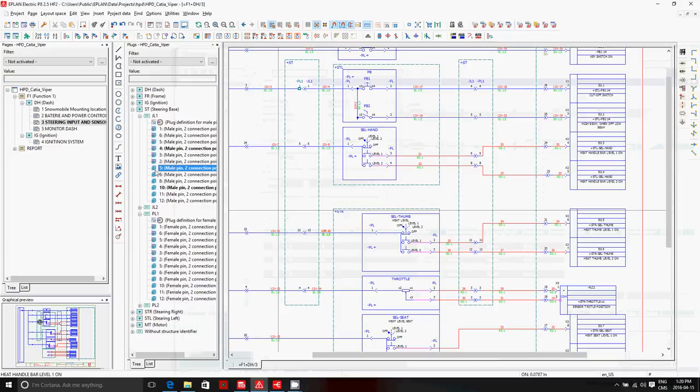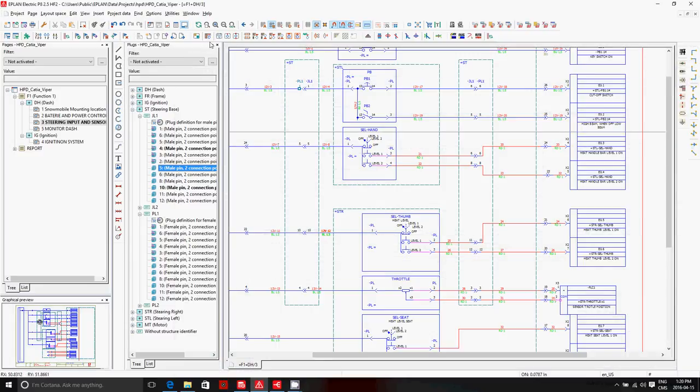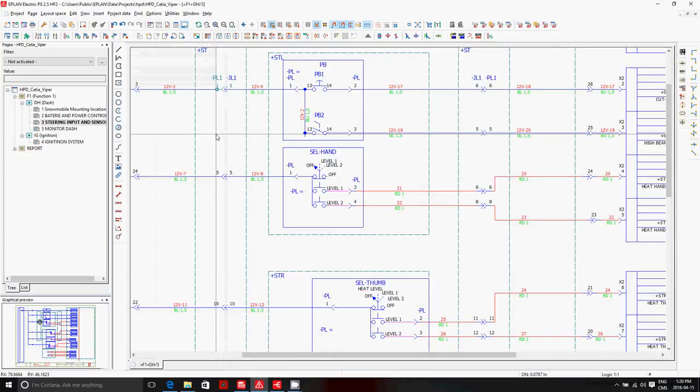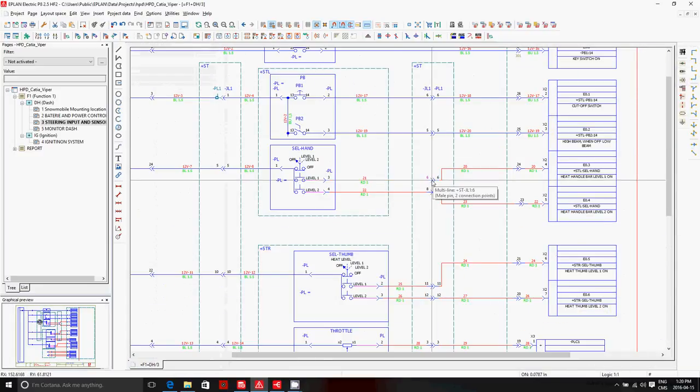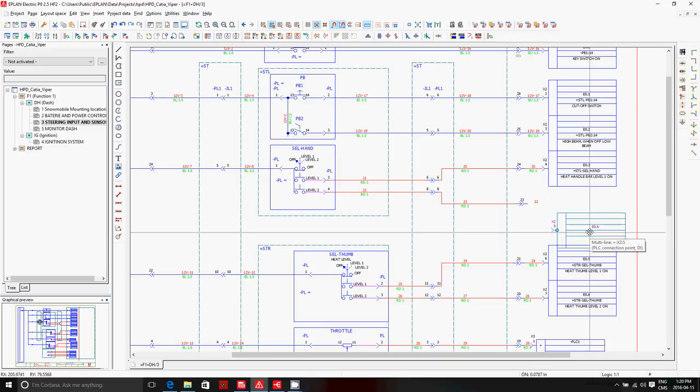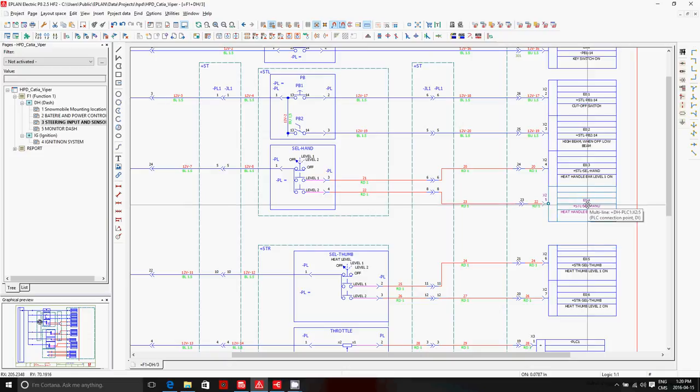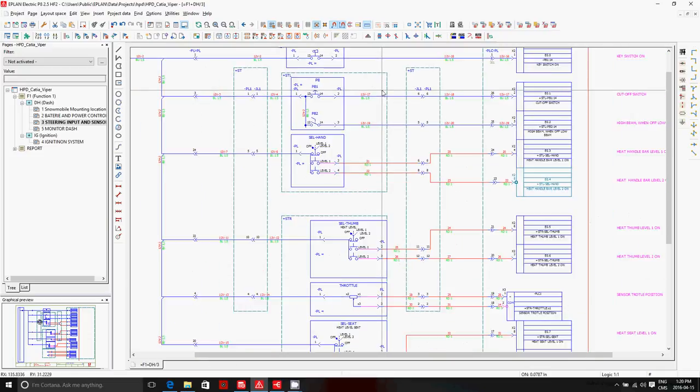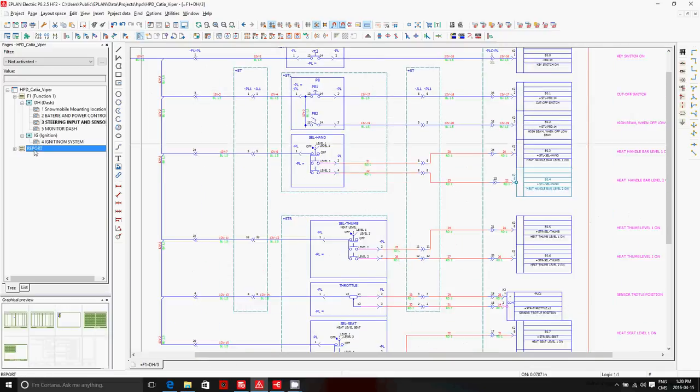So going back to EPLAN, we also have an interesting option drawing the schematics themselves, because in EPLAN, every time you place an object, you can see that the wires are actually smart connected wires. These objects here, if I unplug the smart connect, there is an auto connect that appears. These have the possibility in EPLAN already at this point in the electrical portion.